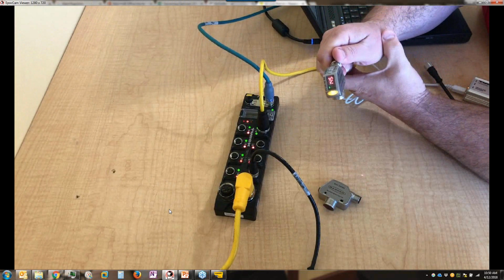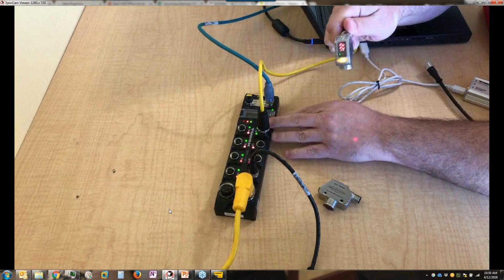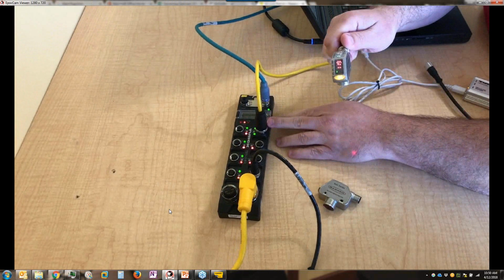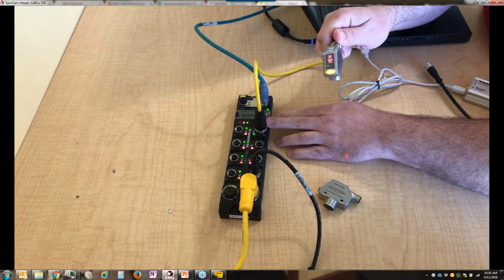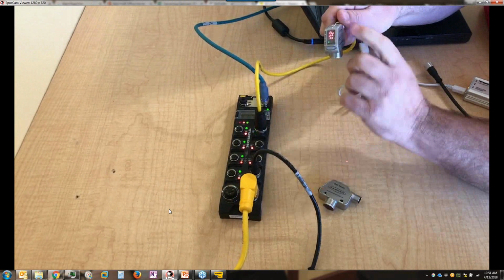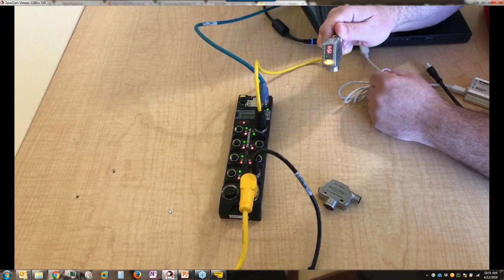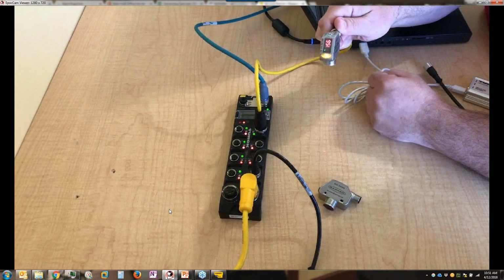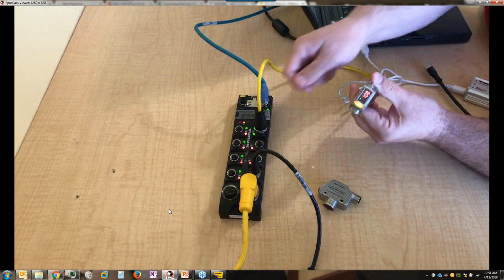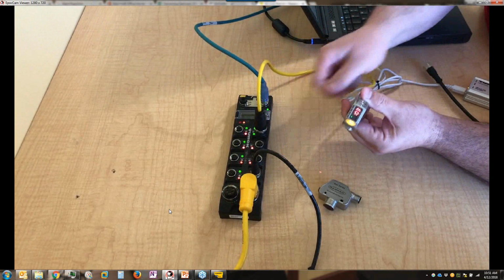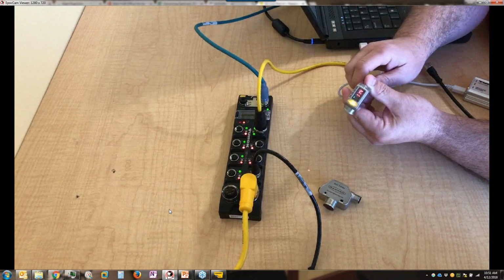Okay. Now remember that this port has been programmed with data storage mode deactivated. In other words, it's not going to back up any parameters from any of the connected devices at all. So it has no effect, regardless of what sensor I plug in. Nothing's going to exchange, read, or overwrite parameters between the two units. Okay.